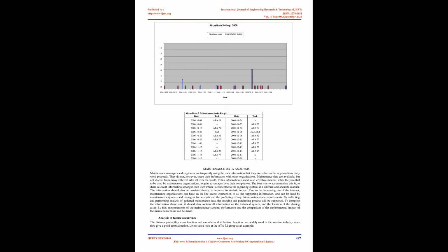When the probability of failure per flight hour is determined for each ATA group, we can determine the defects spread over the year, by randomizing a number between 1 to 100 for each runtime hour during 1 year, i.e. 1,560 times per aircraft and ATA group. Every time the randomized number is equal to, or less than, the probability factor, it will give us a defect, and also which runtime hour the defect occurs.